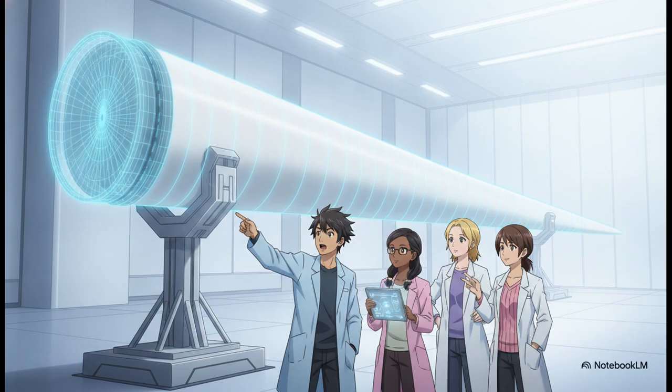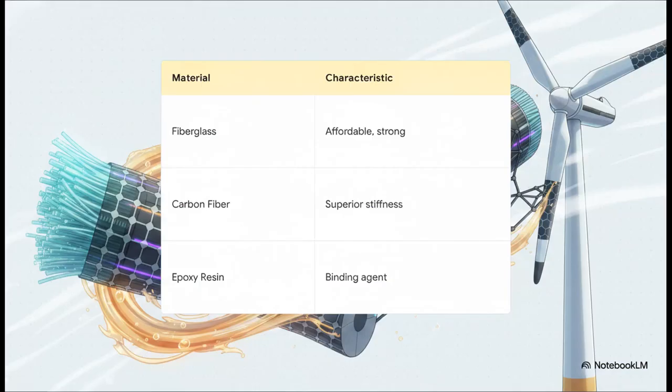Setting the blades completely flat or at just a slight 0 to 5 degree angle changes the game. Even better, engineers twist the blades. They keep them flat near the tip but twist them 10 to 20 degrees near the root to handle the different travel speeds all along the blade's length. It's brilliant. But hey, optimization isn't just about shape, right?